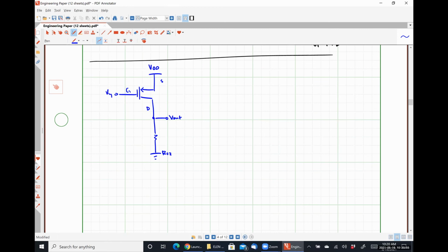So in this case, with this as a PMOS, V out over VY is just going to be negative GM2 R22. I don't know why I wrote R22 way down here at the ground symbol. Negative GM R22. What would our output resistance be? That's another good question, right? Or is that what you were about to ask, Alyssa?